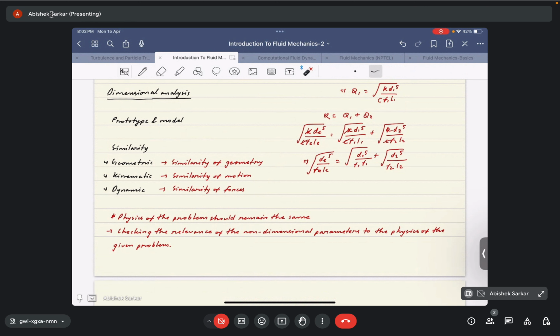But usually for most fluid flow problems, if it is not dealing with heat transfer, it's usually mass, length and time. So there are usually three fundamental parameters, but I'm not saying those are the only ones. In general, I guess there are 7 fundamental parameters, but depending on the problem, the number can change. For most of the fluid mechanics problems that we're going to deal with, the fundamental parameters we will have in hand will usually be 3.